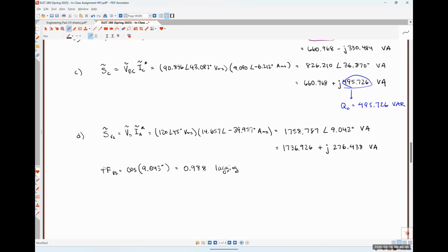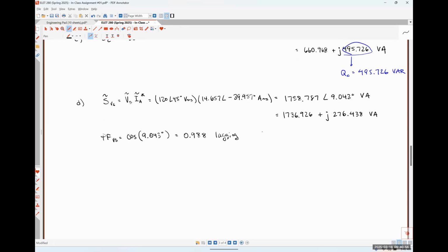Okay. So we calculated our complex power supplied by our voltage source by doing Vs times IA conjugate. Another way that we could have calculated that quantity SVS. So let me just put alternative number one. The complex power supplied by our voltage source has to be equal to the complex power absorbed by all of those impedances, right?